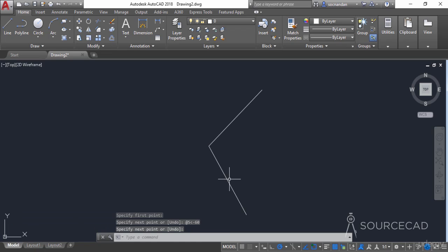You can also use a positive value, or you can use 300 degrees for making the same line. That will be 180 degrees plus the additional angle, which makes 120 degrees here, and that will be this minus 60 degrees angle. So this was all about using different distance entry methods in AutoCAD and making lines with them. And from the next lesson, we'll start making some of the other simple geometries in AutoCAD.